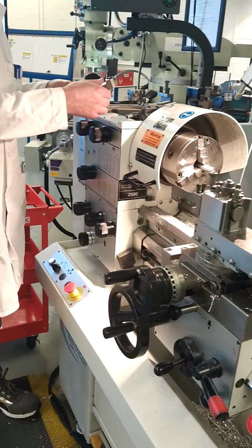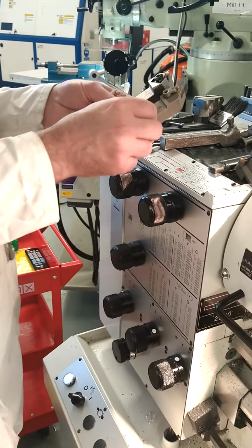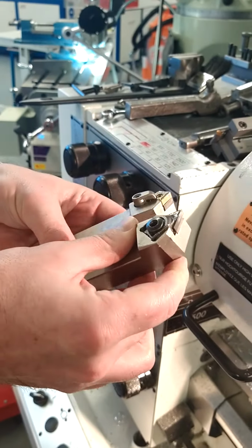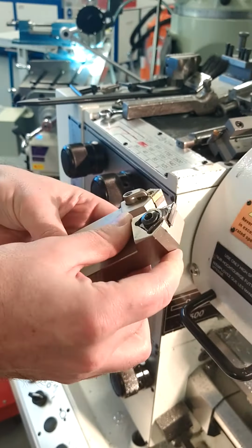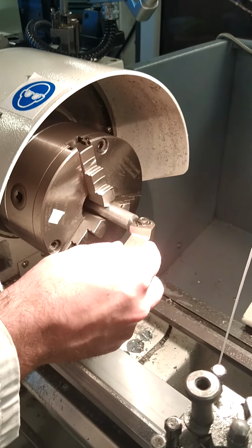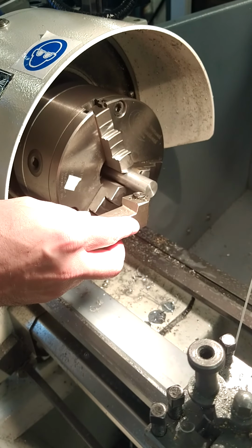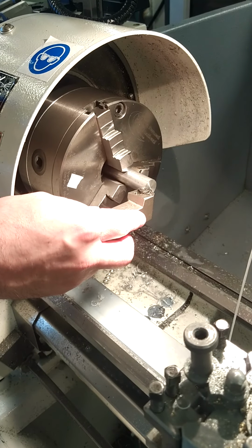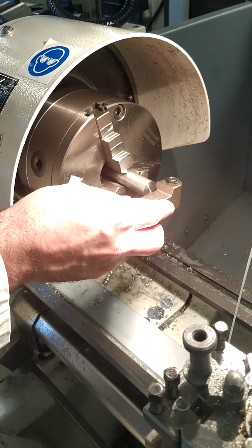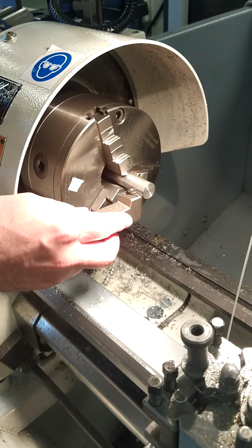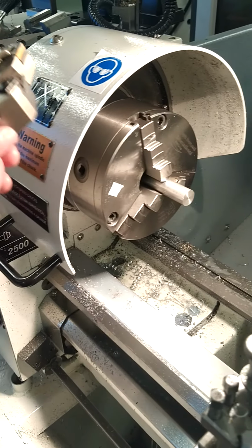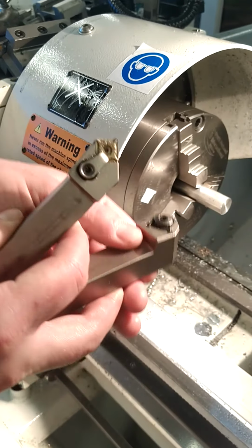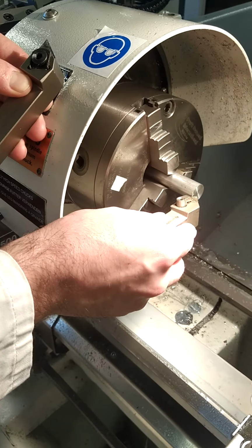So we have a range of cutting tools up here. We have a turning tool, which is for your facing and turning down the diameter of a bar. To face off, we can machine across in this position, and to turn down, we're coming along the Z-axis on the carriage to reduce down the length of the bar. To reduce down the diameter, you're moving in the X position, and to reduce down the length, you're moving in the Z position.